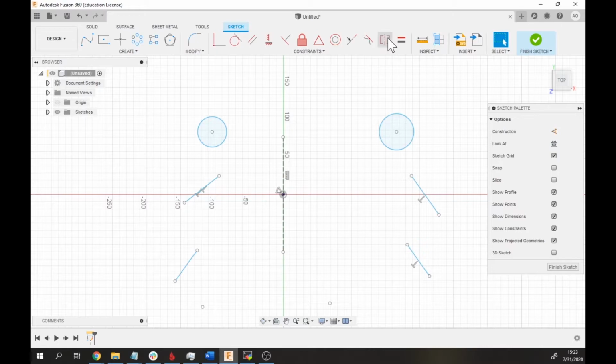So what symmetry will do is if we set it here, you'll notice that those two pop into symmetry with each other. They're both vertically symmetrical and symmetrical across this way. Essentially what this is doing is creating a mirror between these two. You'll also notice that they don't have to be the same size because I set the point symmetrical.